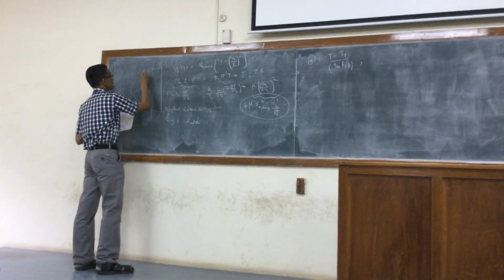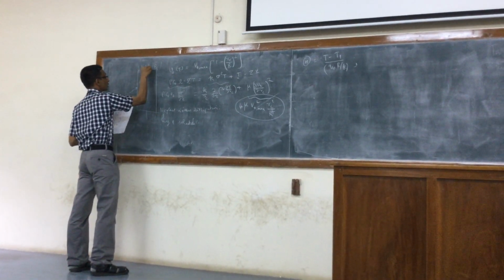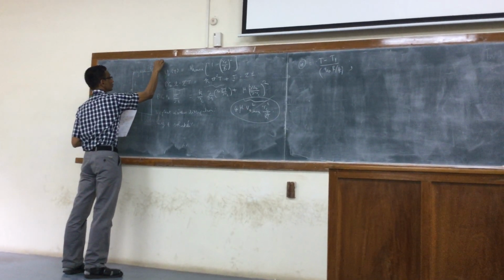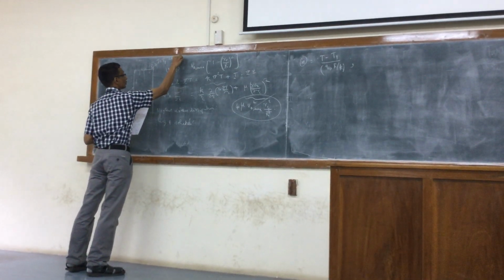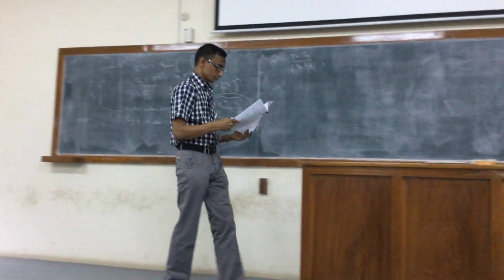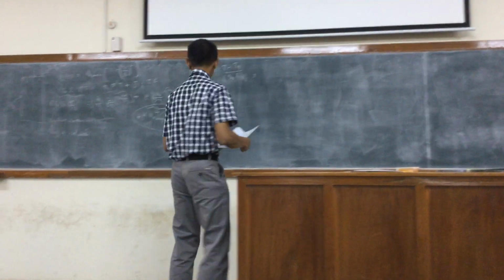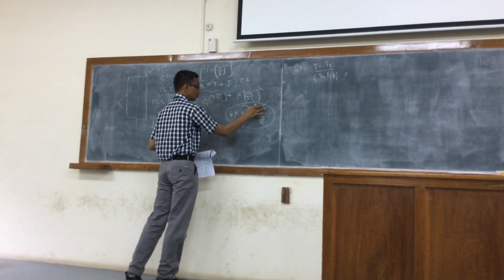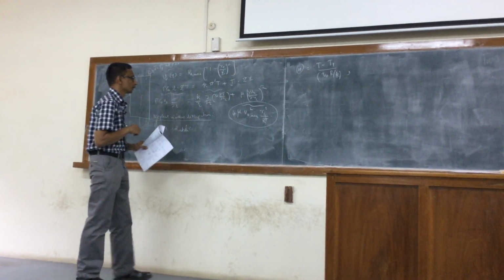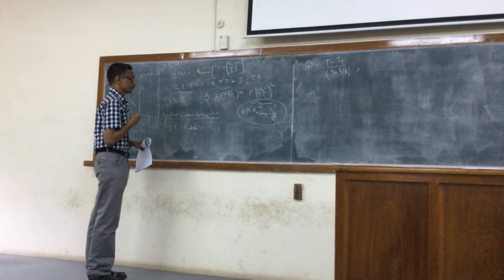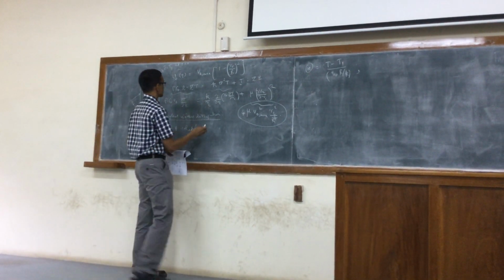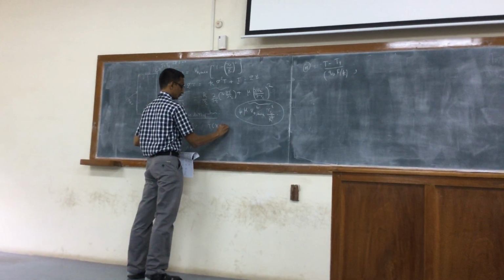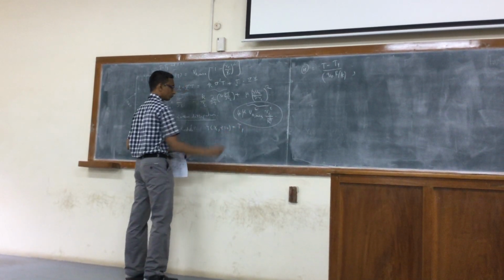The fluid is flowing in with temperature T equal to T1 at Z equal to 0. That's the boundary condition. So the solution is considered for viscous dissipation, and the term can be there as it is, so that you can see what complications arise when you include it. The boundary conditions we have to write: T at rc, Z equal to 0 is T1.